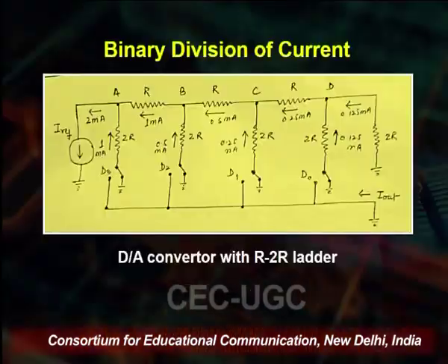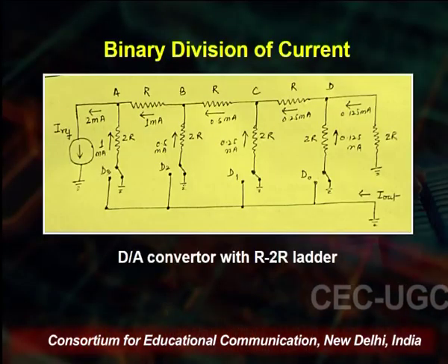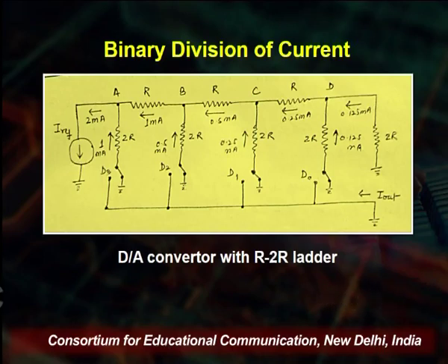So, moving forward, we see that this is the circuit for a DA converter with R2R ladder network. As we can see, in this case we are using a constant current source, which you can see on the left of the screen. That constant current source supplies the current that is collected by the circuit via, again, 4 switches in this case.